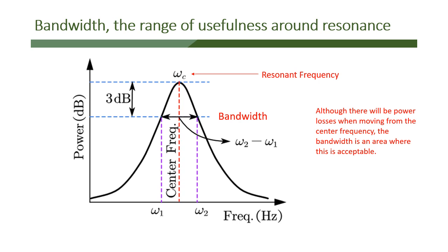And that 3 dB tells me how much power loss is acceptable, which defines the bandwidth of this antenna. But again, if the frequency is 14.2 megahertz, then we would love to see the bandwidth be somewhere between 14 and 14.35 megahertz, because that happens to be the voice band of the 20-meter band.